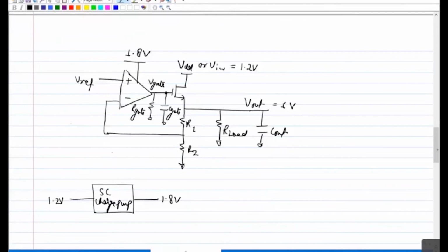So even if your efficiency is 30%, 20%, or 50%, overall system efficiency may not get impacted because it's only a fraction of the power. Efficiency will matter mostly when the power you are delivering from that regulator is a large fraction of your total system power.